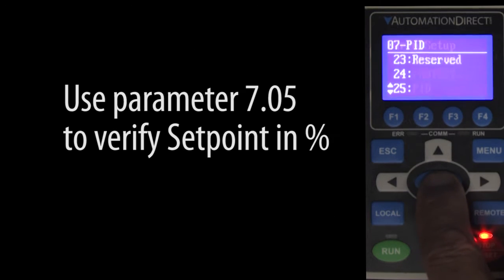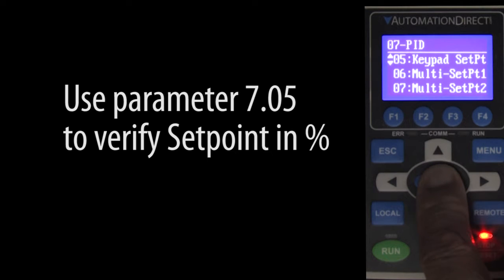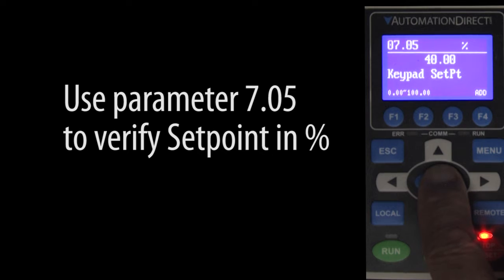And look at this. You can always check that you got it right by looking at parameter 705. It shows you the current set point in percent. Yep, 40%. Perfect. Remember, while our set point is coming from the keypad, you can have it come from an analog input or even a remote PLC. So this is a great way to verify the set point is what you think it should be.